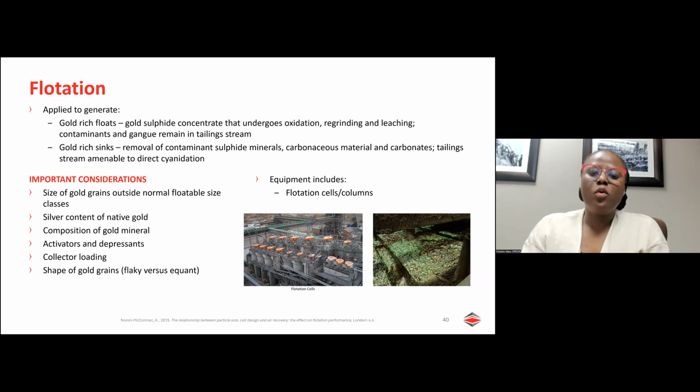Then if your main minerals within your stream are gold sulfides or arsenides or tellurides, then flotation is going to concentrate your stream in the floats, because your main mineral is maybe a telluride or arsenide. And this will leave your contaminants behind in the flotation tanks.